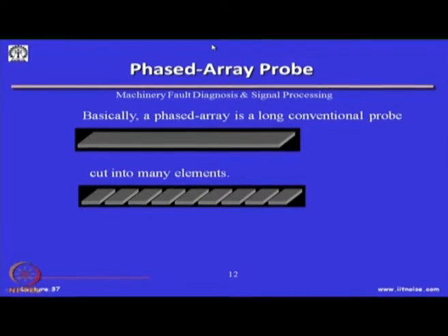Now, we will come to another technique, because by now you must have realized that with ultrasonic I can have a probe, generate a wave, and see its reflected intensity. By measuring the reflected intensity, we get a couple of things. One is the flight time duration, which can be used to measure the thickness, and if this thickness change is because of scale formation or corrosion, we can find out the change in thickness.